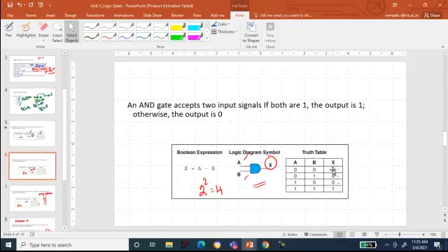And next is your AND. So this is your binary multiplication. X is the output, A dot B is the input. So two inputs you have, 2 power 2, 4 possible input combinations. So 0 0, 0 1, 1 0 and 1 1. Since it's multiplication, only for 1 and 1 you will be having 1. The rest all output is 0.